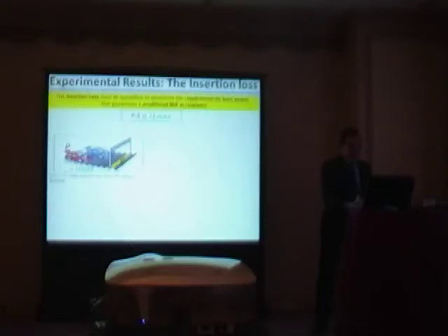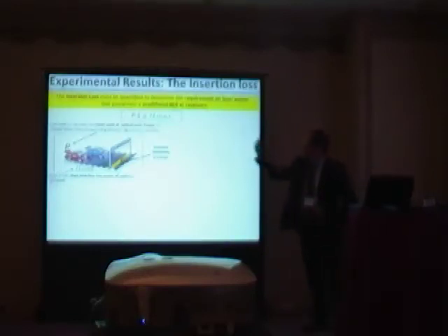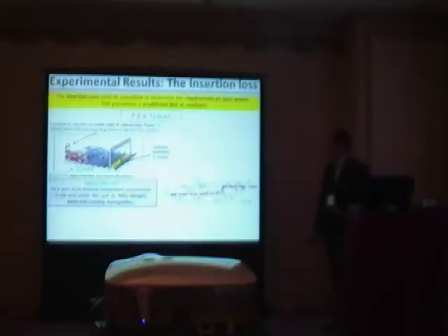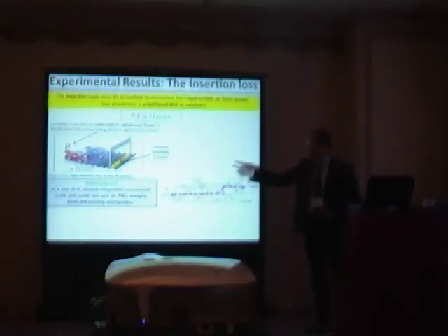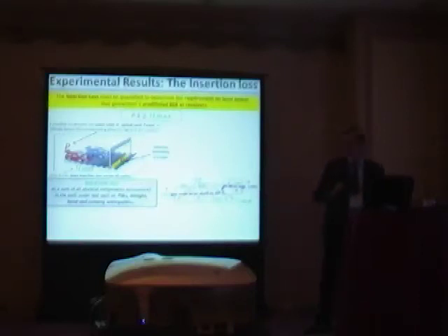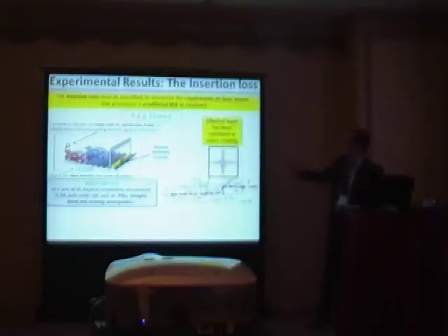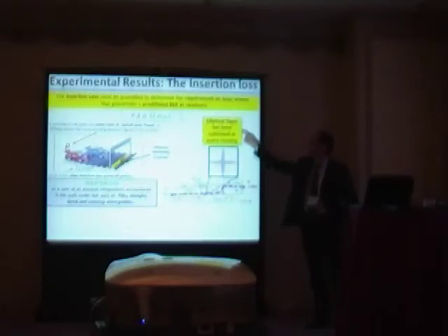As you can see here, once the max insertion loss across all paths, IL max, is obtained, and the detector sensitivity is known, it is possible to determine the lower limit of optical power to correctly detect the optical message at the receivers. Trivially, insertion loss is given by the sum of all loss parameters in a given path, such as drop, straight, bend, and crossing losses, of all components combined on a particular path. Also, in our work we assume that every crossing was optimized by using the standard elliptical taper, like this.